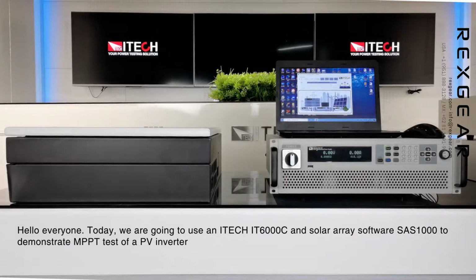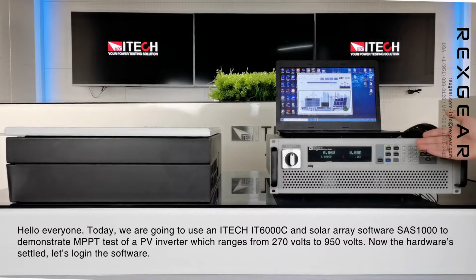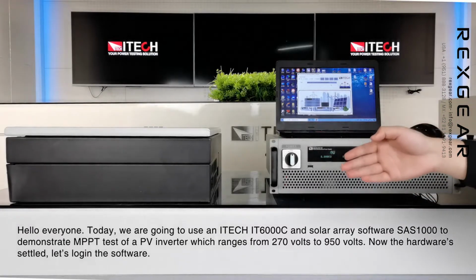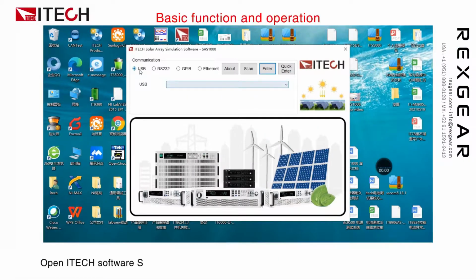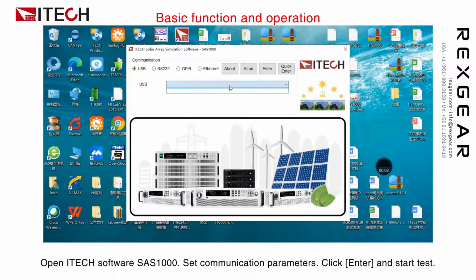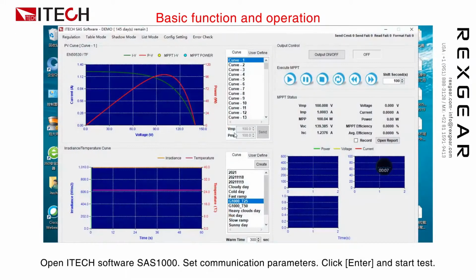Hello everyone. Today, we are going to use an ITECH IT6000C and Solar Array Software SAS1000 to demonstrate an MPPT test of a PV inverter, which ranges from 270 volts to 950 volts. Now the hardware has settled, let us log in to the software. Open ITECH software SAS1000. Set communication parameters. Click Enter and start test.